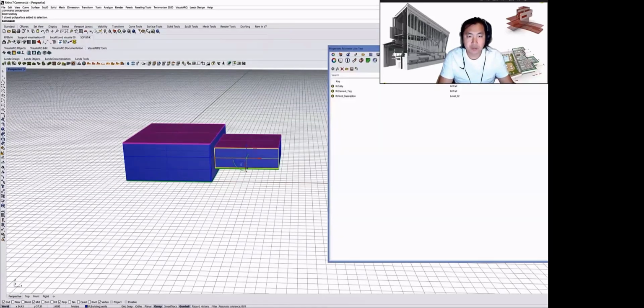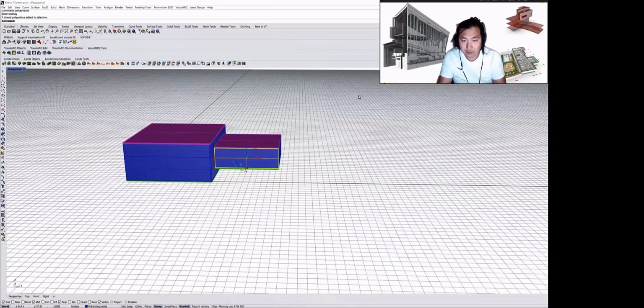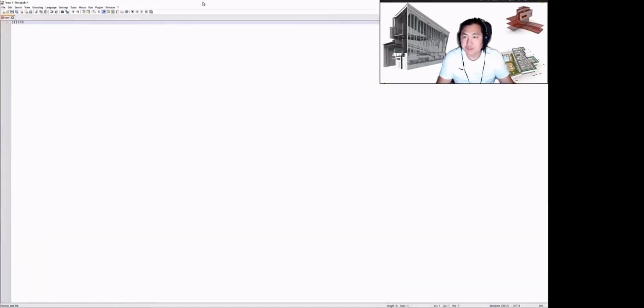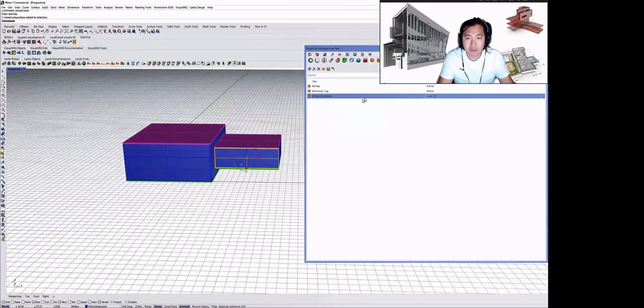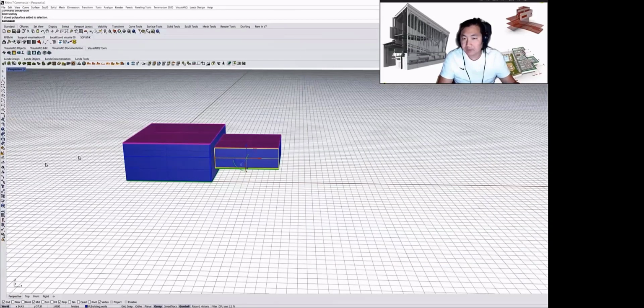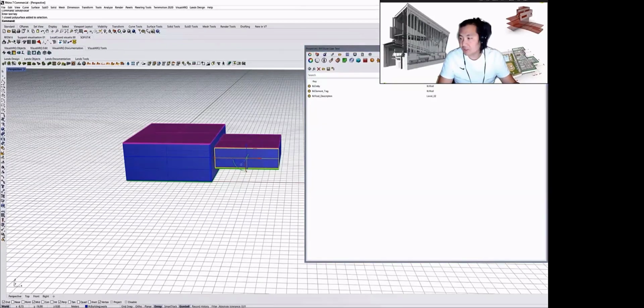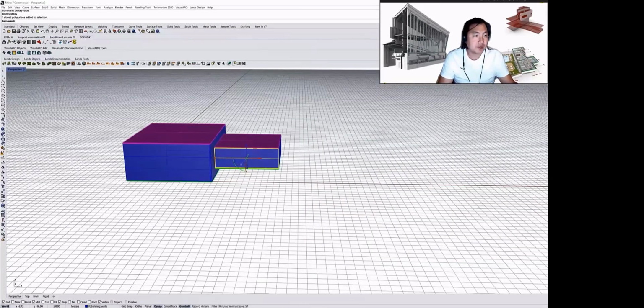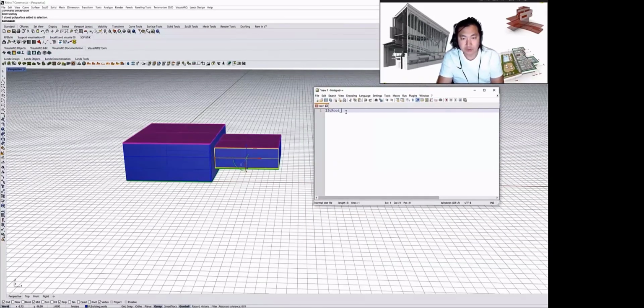So what I'm doing here is referencing the Rhino attribute, for example IFC root description, as one of the main key values, and I would like to restructure the IFC building story in Rhino, so we can have very articulated building levels in the IFC structure.